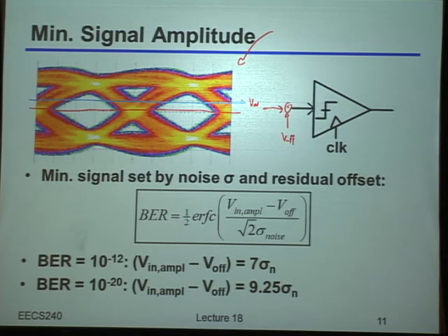Now, of course, if we have some thermal noise coming into our very simple receiver, which in this case is just a comparator, the picture that we drew is we said, well, we could take the probability distribution of the noise, which, just as an example, let's say it's Gaussian. And I'm drawing it on its side here, just because it makes it a little more clear as to what's going on. In the vertical dimension, that's the magnitude of the noise. And in the horizontal dimension, that's the probability of the noise being that large. So this is literally the PDF of the noise of the receiver.